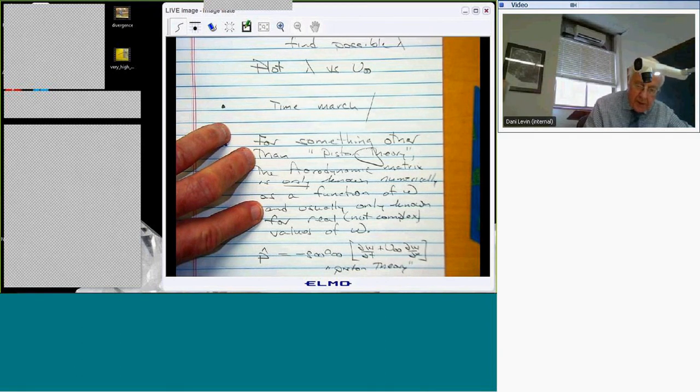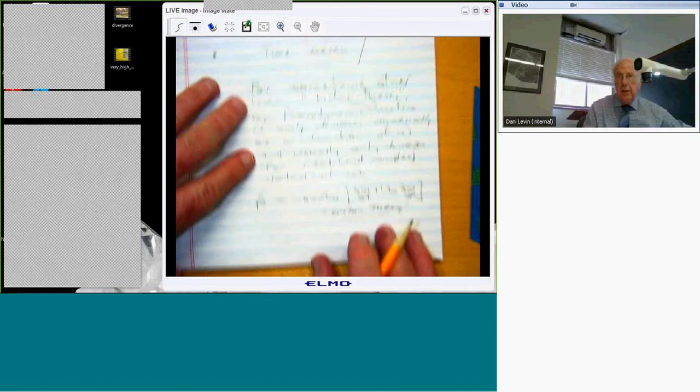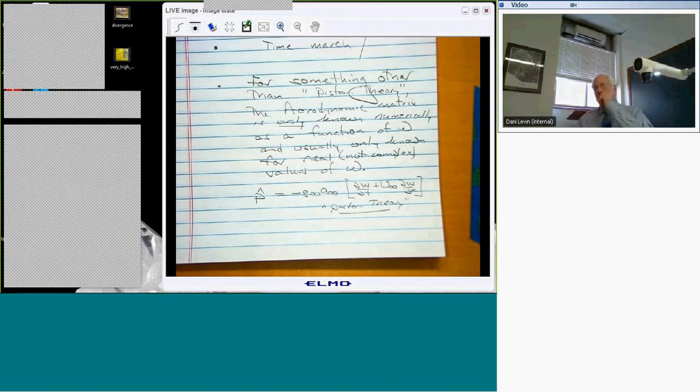And it's a theory that's useful for Mach numbers, supersonic Mach numbers above 2. Yeah, and it was late coming to the aeroelasticity game because people didn't fly supersonically for a long time, right? And the initial theories, and the ones we'll discuss at the end of the course, are actually much more elaborate than piston theory. But you're not ready for that. At least I'm not ready to discuss that yet. So what I'm saying is,